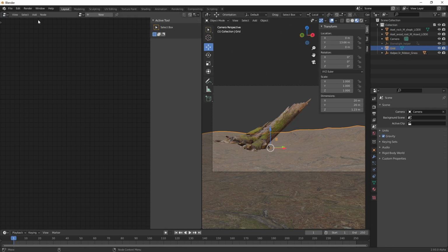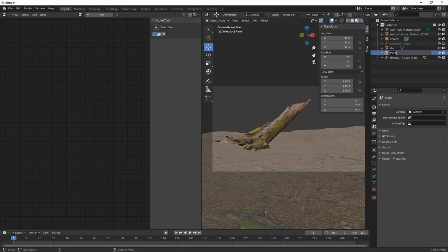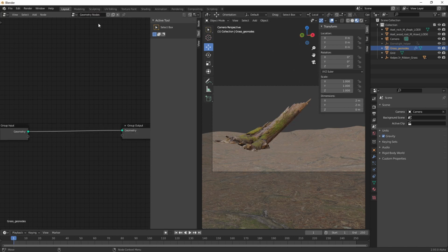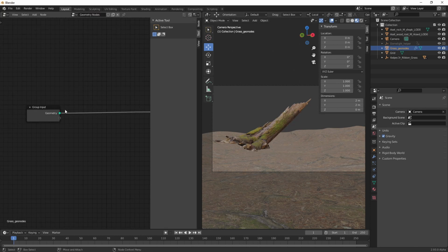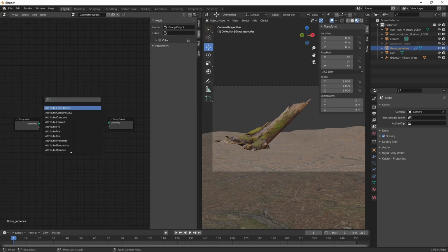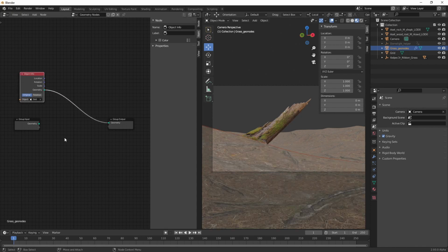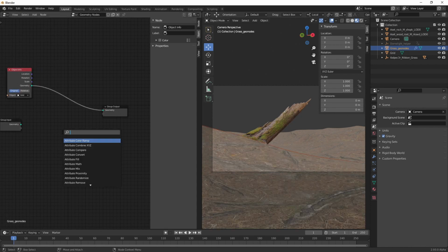Right, and now we're going to go over to our geometry node editor, and we're just going to create a new plane. We'll call it grass. And then geo nodes, just so we know we're going to create our geo nodes in here. Remove this. We're going to object info. We're going to pick our floor. Now we imported the floor.